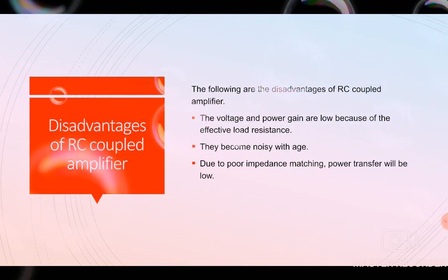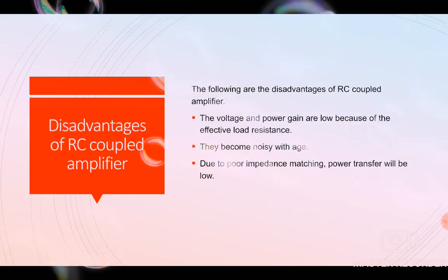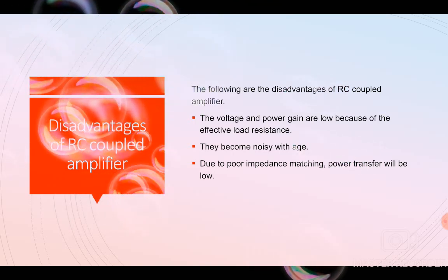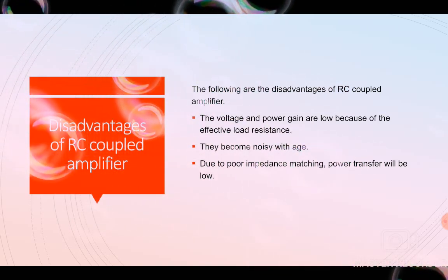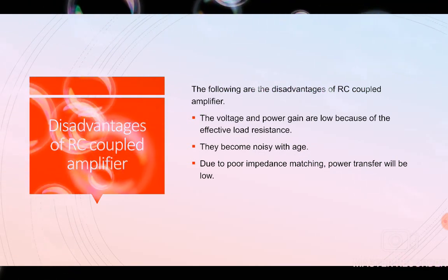Disadvantages of RC amplifier. The voltage and the power gain is low because of effective load resistance. They become noisy with age. Due to poor impedance matching, power transfer will be low.